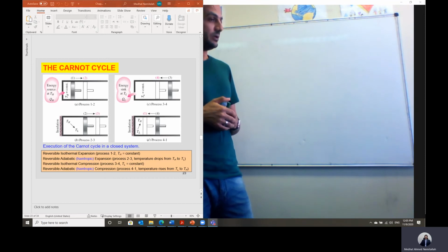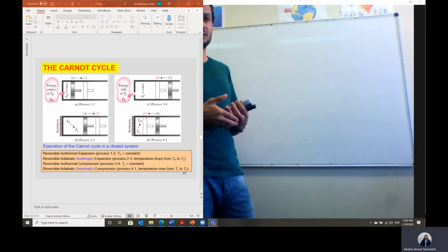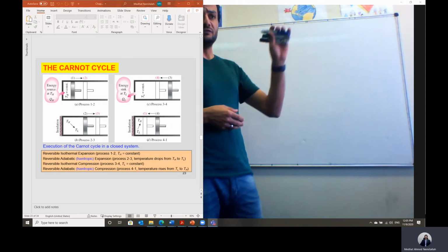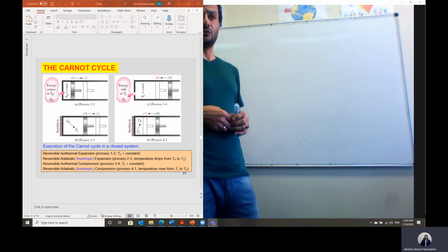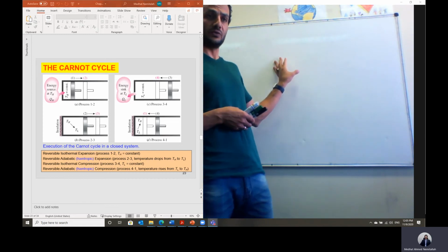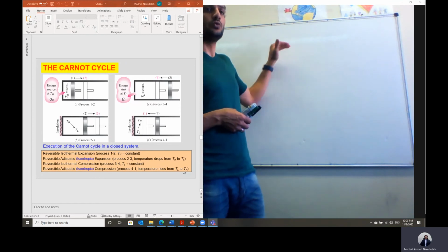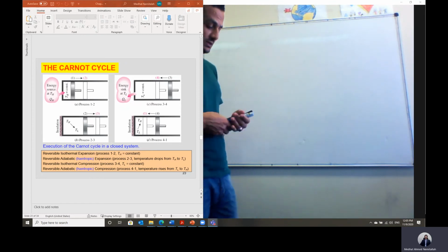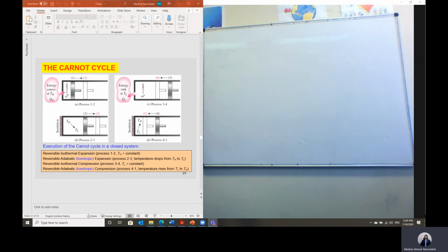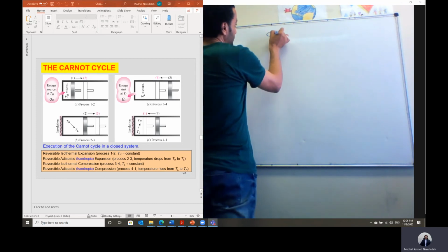And this is a common question for you. I say there is a guy, he claims that we have, let's say, a heat engine that gives a given efficiency. Is this claim true or false? So in this case, I will be calculating the maximum efficiency using the Carnot cycle and compare it with the given value. Then the given value should be less than the one calculated by the Carnot cycle. Okay, let's proceed with the Carnot cycle and see how we can apply it to a heat engine or refrigeration cycle and how we can calculate the maximum performance of this system.